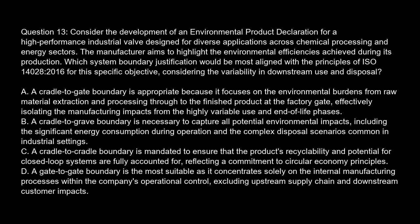Option A. A cradle-to-gate boundary is appropriate because it focuses on the environmental burdens from raw material extraction and processing through to the finished product at the factory gate, effectively isolating the manufacturing impacts from the highly variable use and end-of-life phases. Option B. A cradle-to-grave boundary is necessary to capture all potential environmental impacts, including the significant energy consumption during operation and the complex disposal scenarios common in industrial settings.